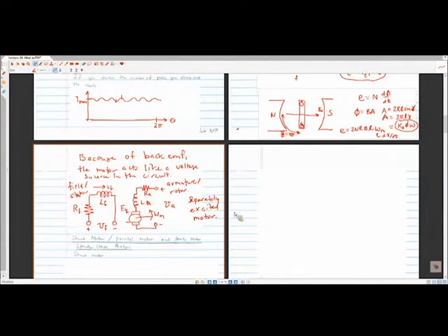Okay, so the whole purpose of this is just to give you the most general circuit diagram for a DC motor. And then we'll get into some specific forms in a second. The reason I say it's general is because this has two voltage sources, right? So you can have a voltage source for the armature or rotor, and a voltage source for the field or stator. So that's 4 terminals.